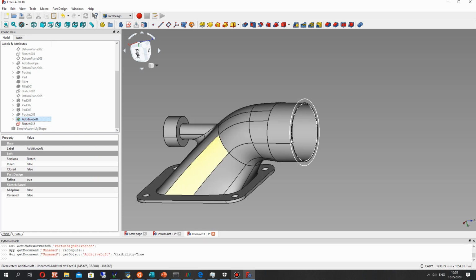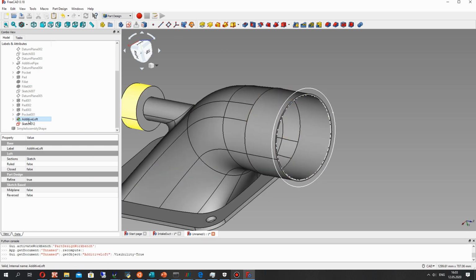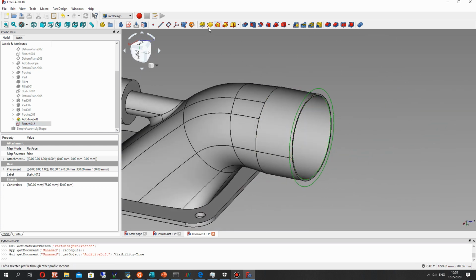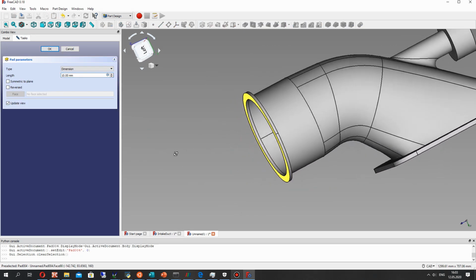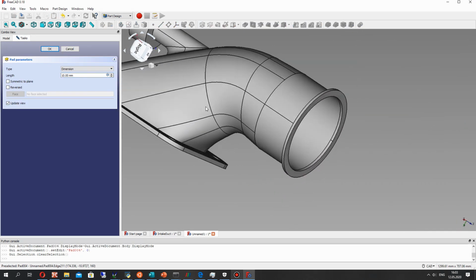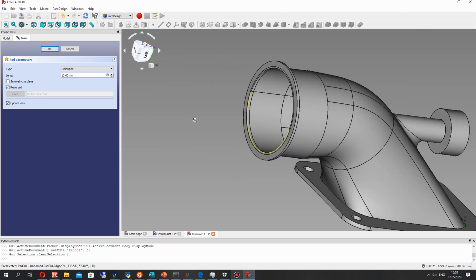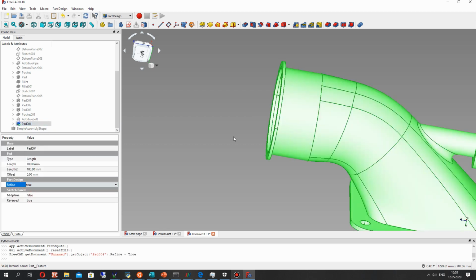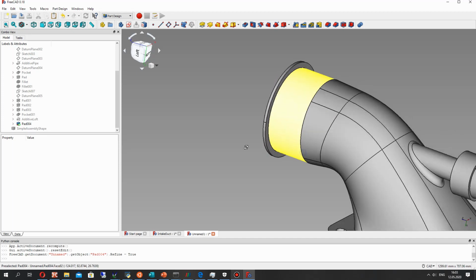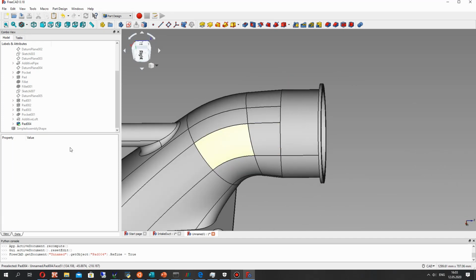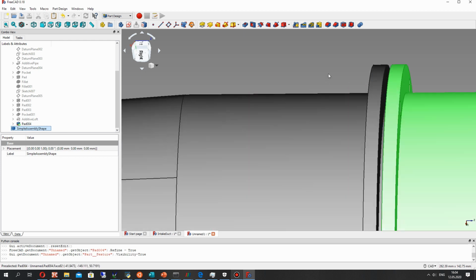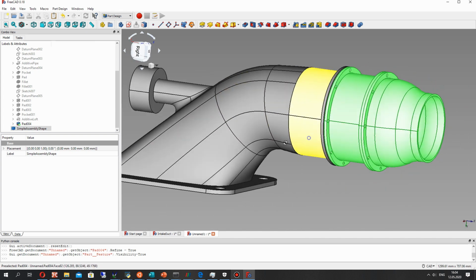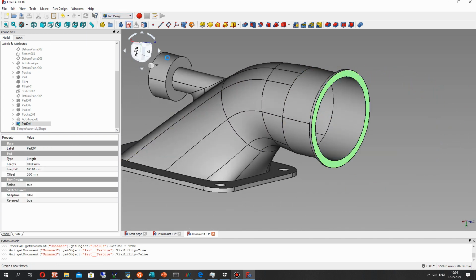Okay, and we have the sketches of our flange, and we have to make the extrude operation for this. Let's make it. It is bed, and set the thickness. It will be 10 mm thickness of our flange. Okay, and make refine operation. Yeah, we almost finished, and the last operation we have to create the holes on our flange.